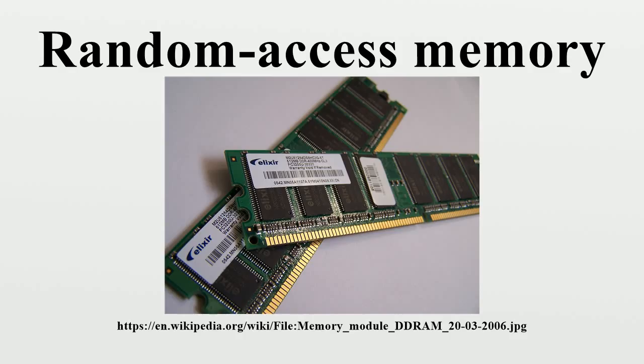As a common example, the BIOS in typical personal computers often has an option called "Use Shadow BIOS," or similar. When enabled, functions relying on data from the BIOS's ROM will instead use DRAM locations. Depending on the system, this may not result in increased performance, and may cause incompatibilities. For example, some hardware may be inaccessible to the operating system if shadow RAM is used.